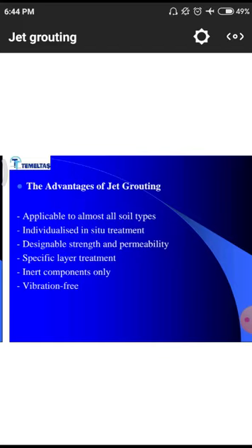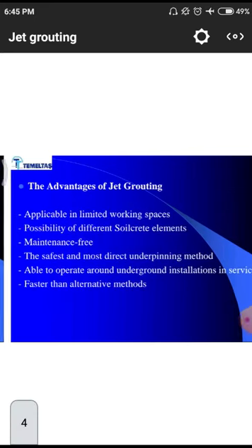Simply, it is vibration-free construction. Why? Because we are pumping the fluid with high flow and jet speed, so the particles will arrange themselves in a rapid way, without any voids, giving high density, so it should not require any vibration measures.